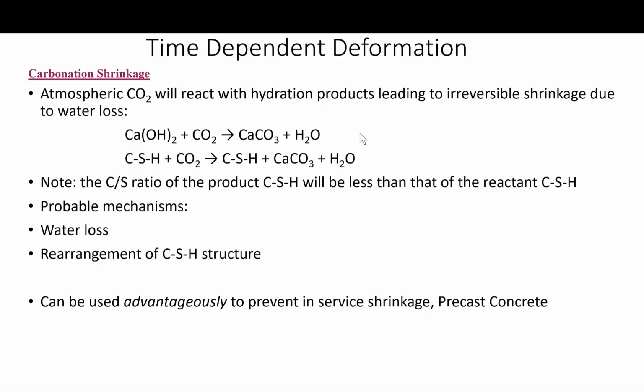Since it's much less porous than the block, for example, carbonation can occur only near the outside and precisely where the maximum rate of drying is also occurring. Okay, so carbonation shrinkage is likely to be maximized, and when added to drying shrinkage may cause severe shrinkage cracking.